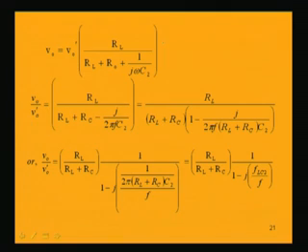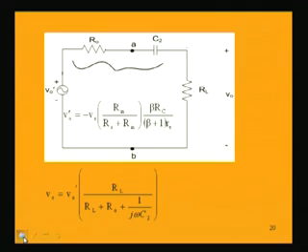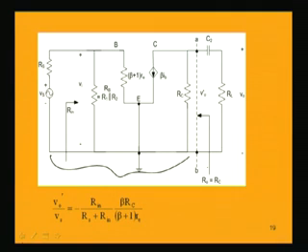Now, we find V naught equal to V naught dash into this quantity, which can be further simplified. So, now we will take the ratio between V naught and V naught dash, that is equal to RL by RL plus R naught. R naught can be replaced by Rc, because if we look into the circuit, R naught, the output resistance, when I look from the output terminals, is nothing but only Rc, because Vs has to be short circuited and that makes IB 0.